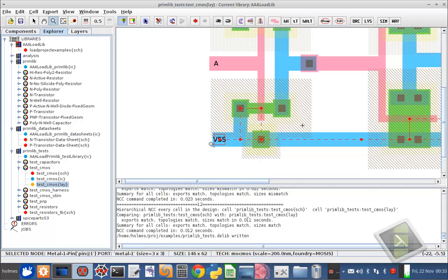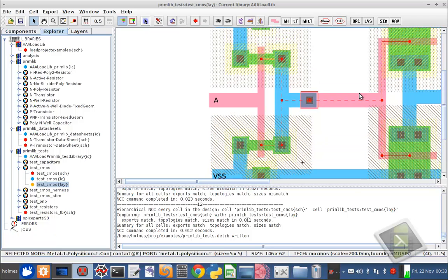And so just by highlighting a signal, you can get a very clear view of how things are connected in the different runs. And this is really a valuable aspect of Electric, where you can see the networks and how they work their way through the layouts to each device. A key thing to keep in mind is that when you see dash lines, that means it's an arc. If you see a solid line, that means that it's showing you the pin.